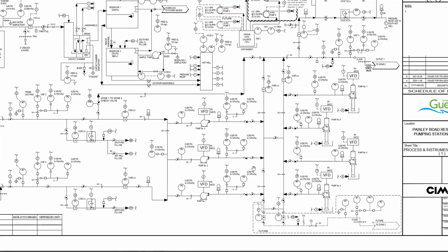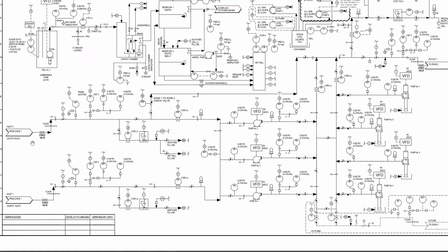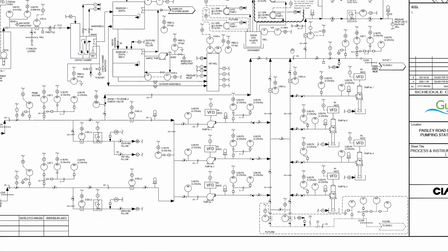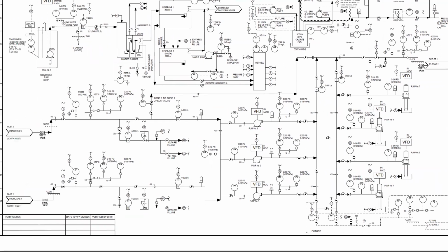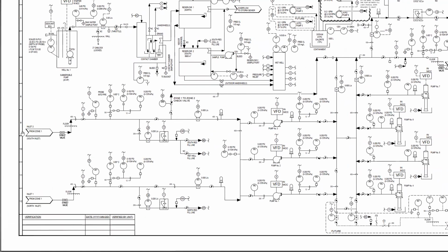It doesn't exist yet, but so now it moves up to a flange, which then connects the hand valve. You can see here that there's a check valve right there. So this check valve will allow us to route water directly from zone 1 around the booster into zone 2 by using the pressure from the upstream pumps.